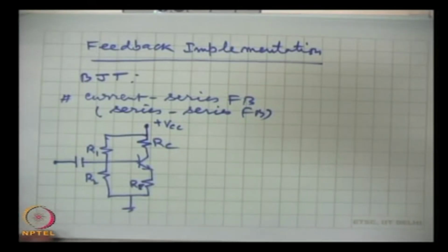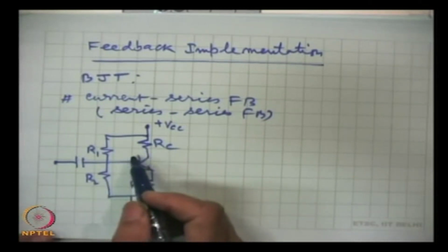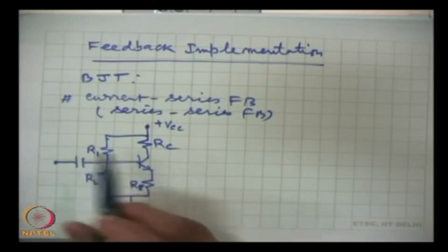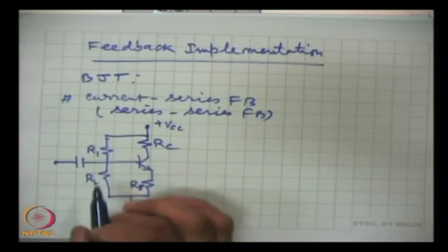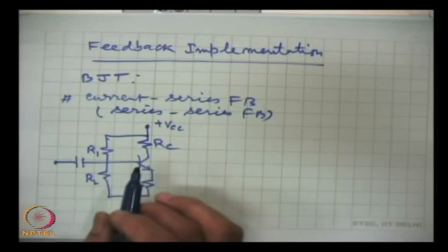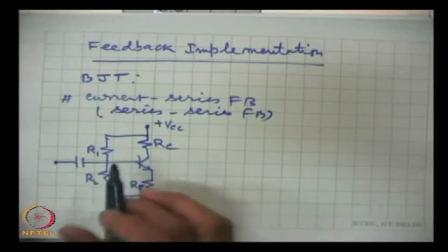Now, the incorporation of this resistance RE is a feedback resistance here, because in the absence of this resistance we have seen that the input is in no way connected to the output and the circuit is highly unstable. Any variations will be reflected immediately in change of the characteristics of the amplifier. For example, rise in temperature will enhance the gain, which is not desired.